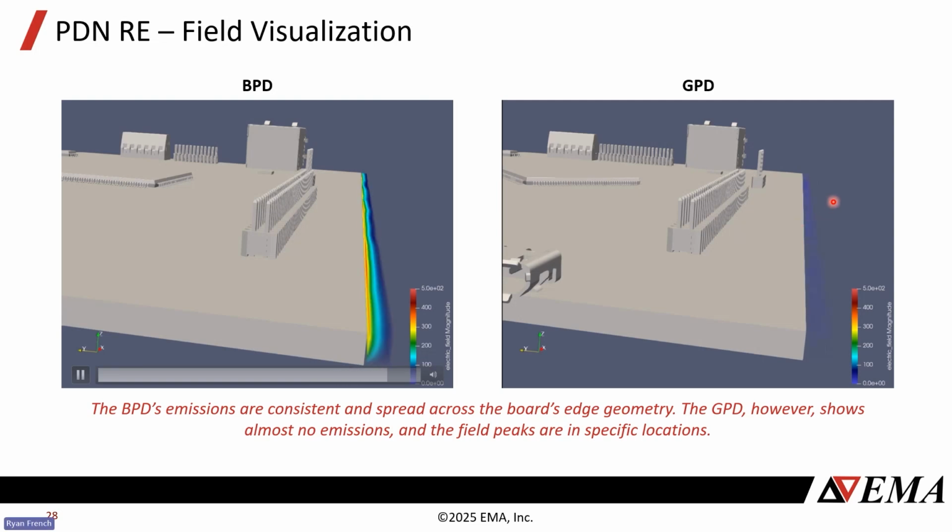You'll notice some developing later. There's a couple of weird peaks, and that's probably areas where the vias were spaced a little bit farther. A lot of what you're seeing at the end of that good design, though, is just a bit of numerical instability in this simulation that I did. So if I were to go in and hunt that down and fix that, we would basically see no fields being ejected from the edge of that good design. So again, PDN, so important. Suppressing resonances, so important.